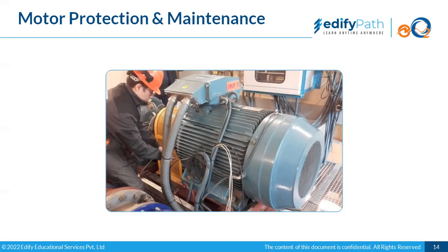We need to have a schedule, so that we keep the production team informed that from this time to this time we would be taking it for scheduled maintenance. Scheduled maintenance helps us protect the motor, because some motors are so sophisticated that if they break down or develop a bigger snag, say the windings have burnt out, and the motor is a 100 HP or 120 HP motor, a huge motor, then even if it goes for rewinding and testing and then comes back, it would take a very long time, 15-20 days.